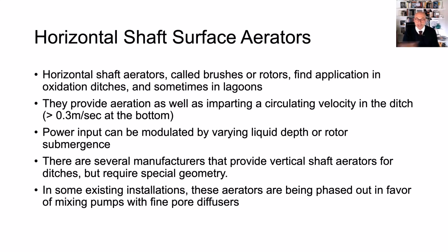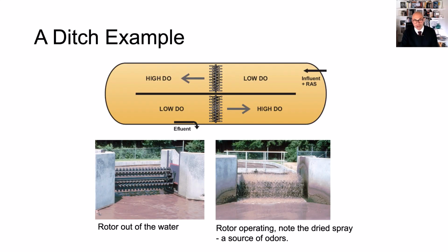The ditch requires the motion back and forth all the time. However, the problem is they're cooling the water a lot, and there is the release of odors and aerosols. And this is an example. You see the rotor could be lifted out of the water when not needed, and goes partially in the water or goes deeper in the water.